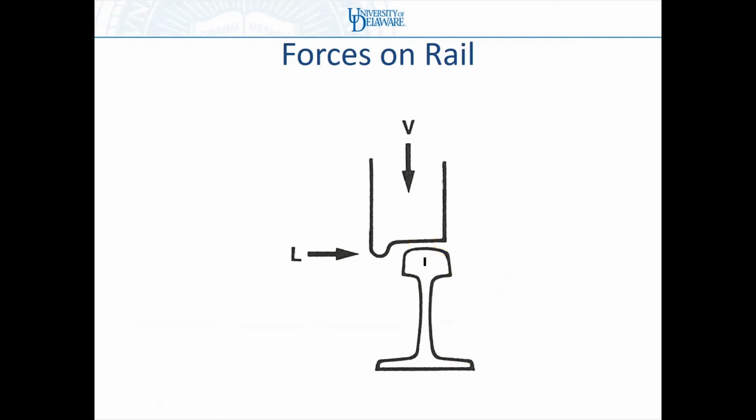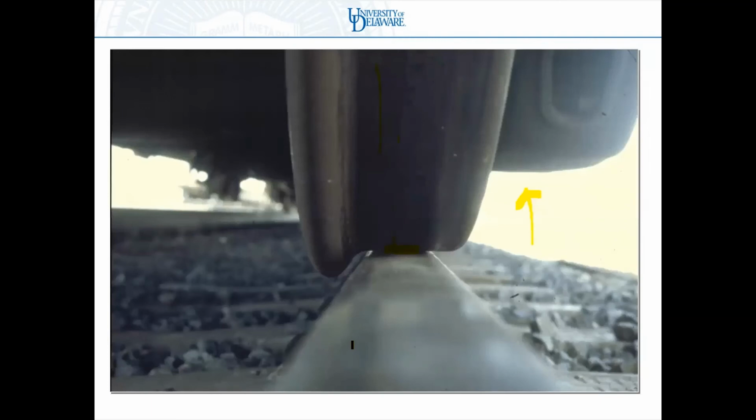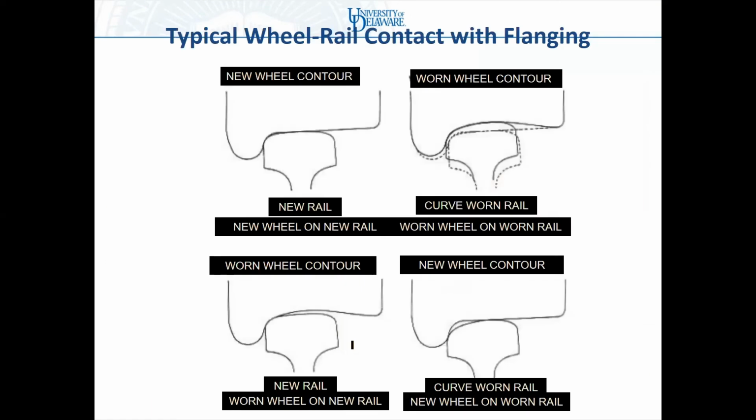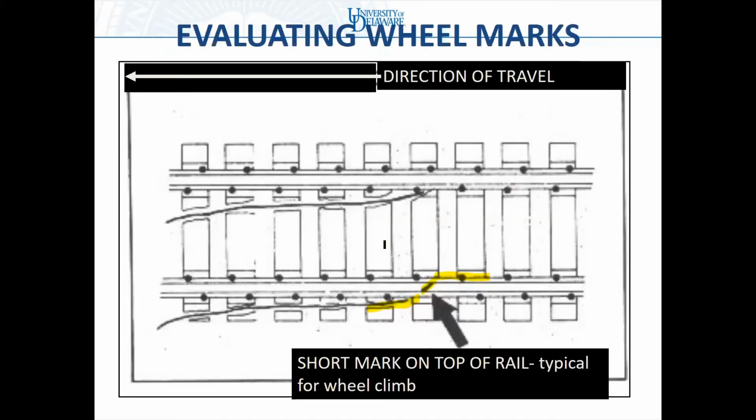I don't rotate the rail enough to roll over, but I rotate the rail sufficiently to widen the gauge. So I have gauge widening, and again, I have the risk of this wheel dropping in right over here. And my L over V forces, of course, are very much dependent on my wheel-rail contact forces, as are my stresses, which we talked about in a different case.